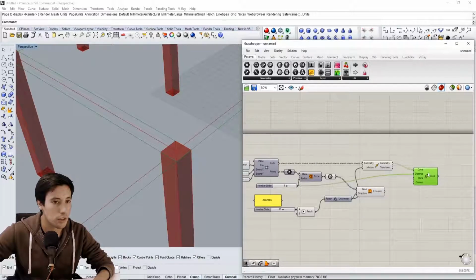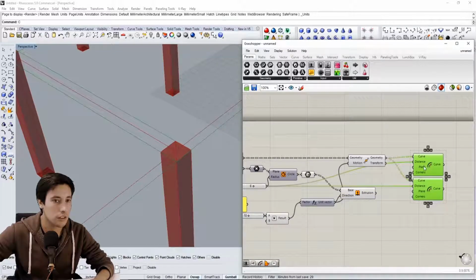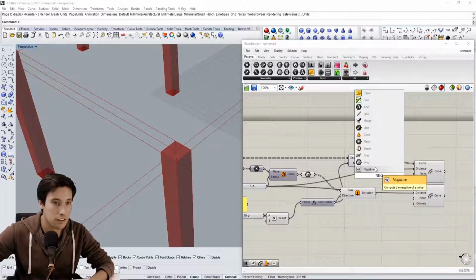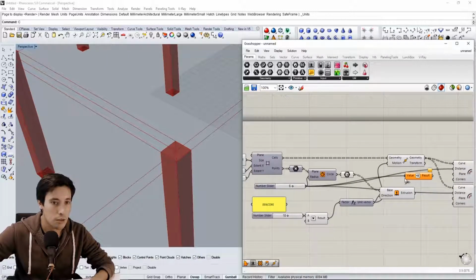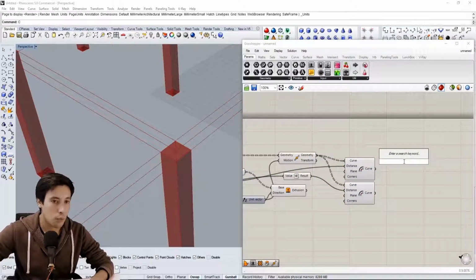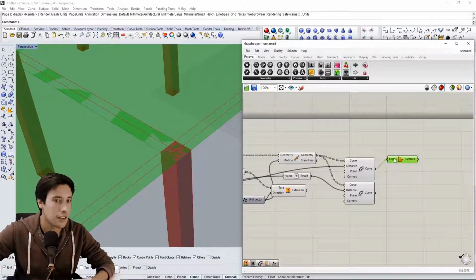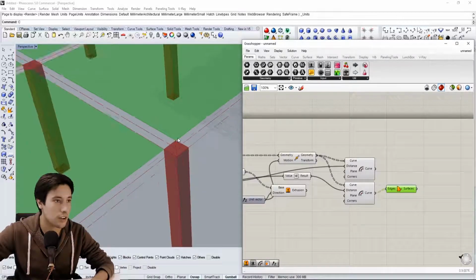But we also want to do the opposite of offsetting. So let's go ahead and drag this down, copy it over with Alt, and come here and go to a negative, so we can take this 6 and turn it into -6, and now we can offset those same curves the other way back. So we have the offset out, and we have the part that's offset in. Now what we want to do is create boundary surfaces for both of these, and so we'll see that this creates a boundary surface on the outside of those cells, and this creates a boundary surface on the inside.